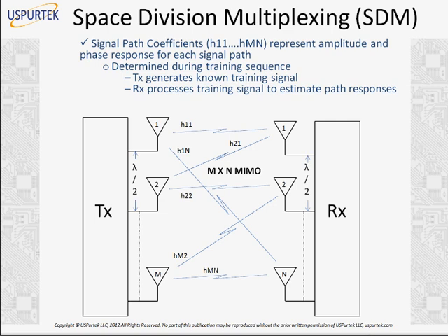So for any MIMO system to operate properly, we must know these coefficients beforehand. Before any communication can begin from the transmit to receive side, we have to determine these coefficients. And that is why each of these standards, WiMAX and LTE, has a training sequence. There is a training period when the handset powers up and tries to establish a connection with the transmitter.